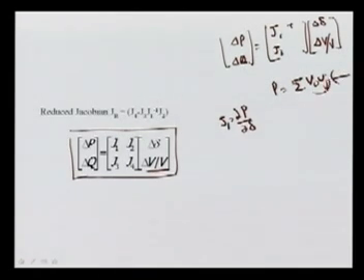So this is quadratic in voltage. If we differentiate this equation with respect to delta, we still get the quadratic in voltage. But if we go for J2, it is nothing but change in P by V, meaning one V goes off. So we try to multiply this to make it quadratic.